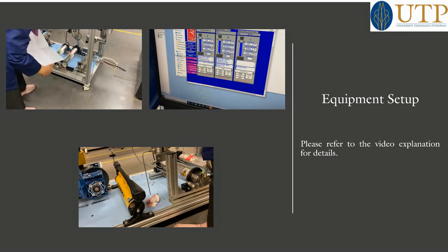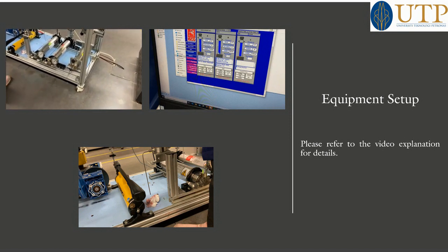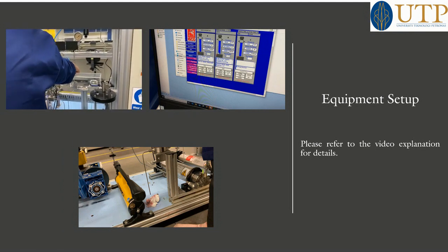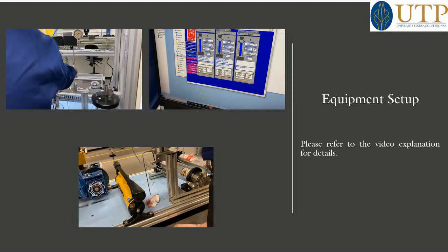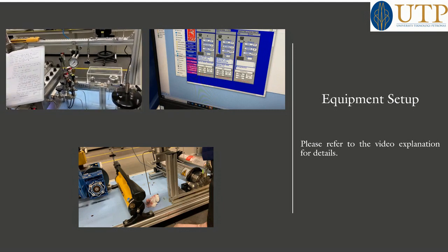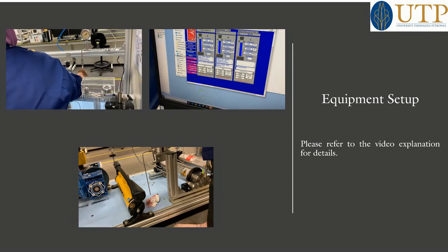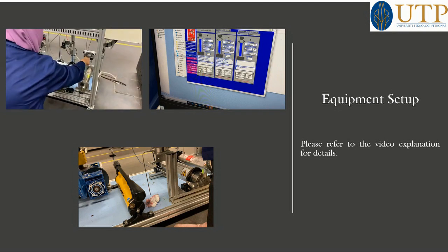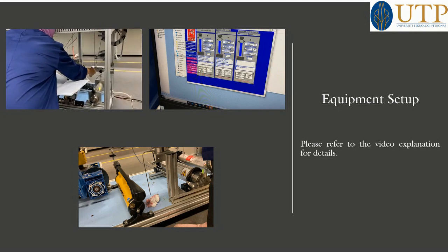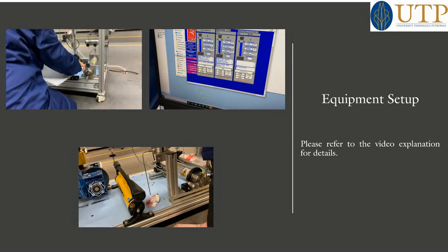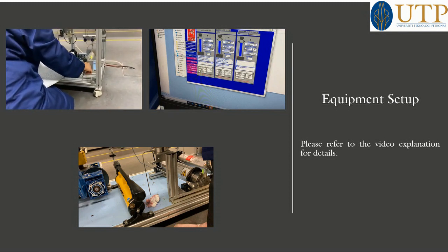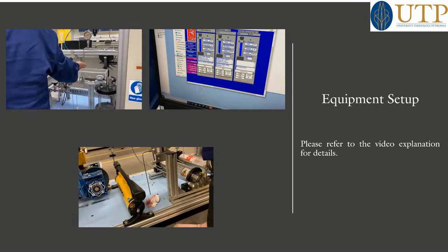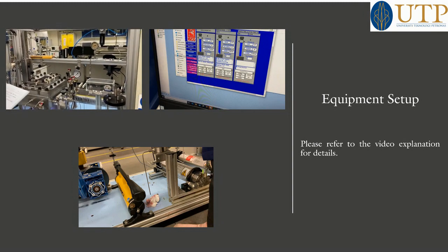And now open V10. So I will open V10 because now my carbon dioxide is still at this point. When I open this, then it will go through the line. So I'm opening V10. That means my gas already goes through this line, and then this one is open already. That means from this line to inside the gas cylinder. Now close it and close V10. So my cylinder is now filled with carbon dioxide, 150 psi carbon dioxide.